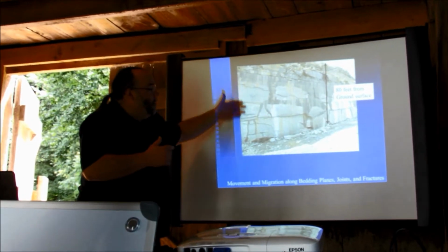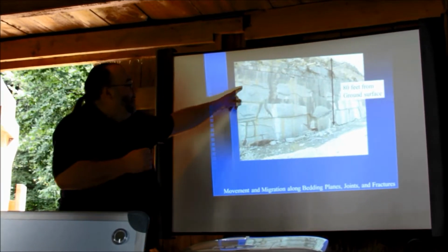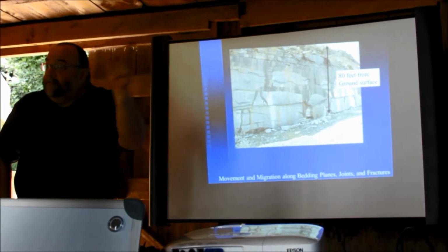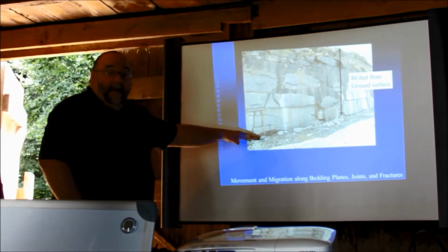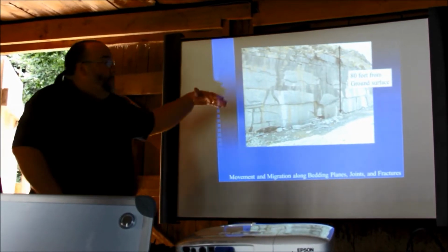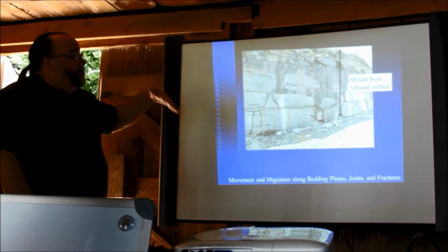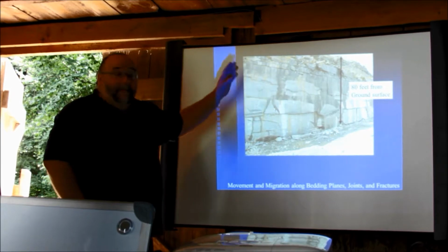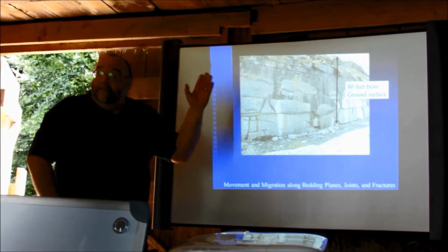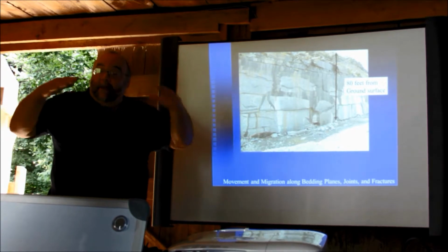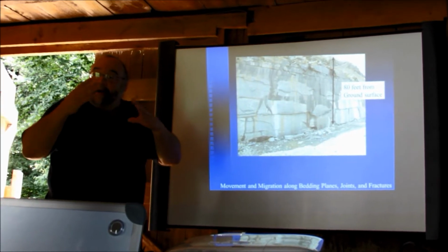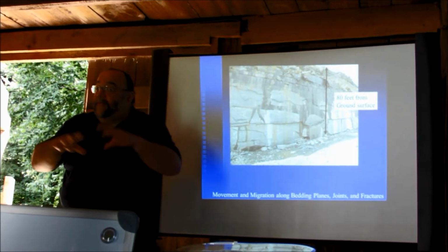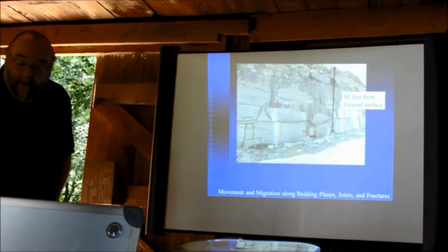And so this is the example. This is a rock quarry west of Dimmock, where you can actually see mud moving along those fracture zones or bedding planes in that formation. We're 80 feet down from the surface. A lot of times when this becomes a problem, it's more of a problem for older private wells that have very little casing, because they may only have 20, 30 feet of casing. As you get closer to the surface, you have bedrock that's more fractured, with more bedding plane fractures, and they're open, so you can have that mud loss. But again, you have to seal more to the surface.